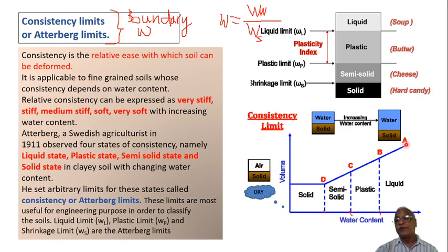Now we'll continue our discussion. When you add a lot of water, it becomes muddy water, or a soup kind of stage. When you have a lot of water mixed with the solids, obviously it is muddy water, right? So it will be flowing, it will be in the liquid state, and it will not have much shear strength. You know that fluids are defined as substances which have negligible shear strength.